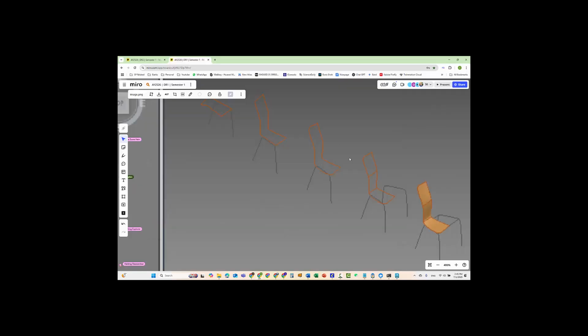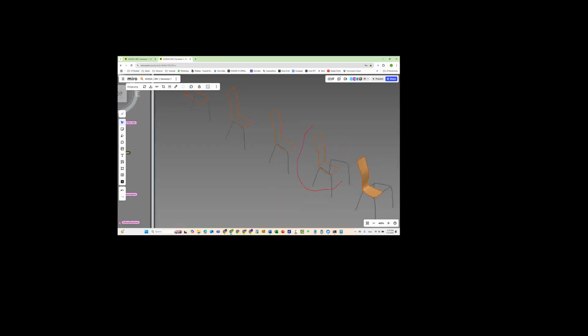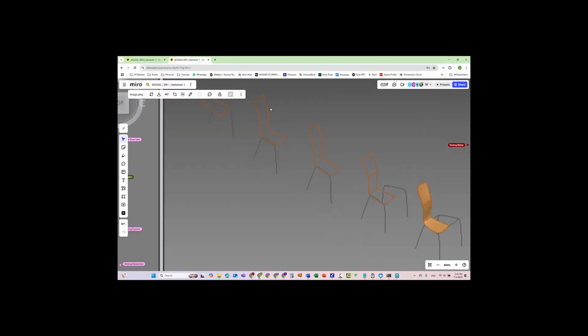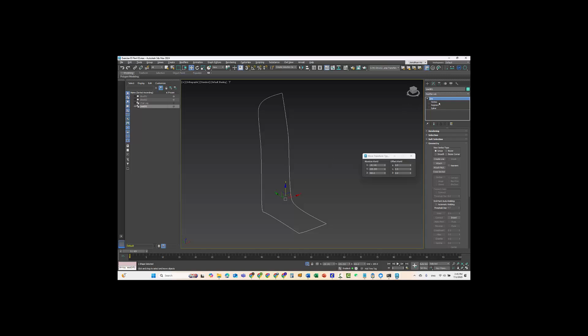Okay, so there's a problem, and what we need to do is to create more definitions for the lines. So that's why, from here, we need to add in two more lines down here and here to create the definition. So what's going to happen is I will go to vertex subselection mode, and then under geometry, I will click on create line and snap 3D right here, and then I will draw one line from here to here.